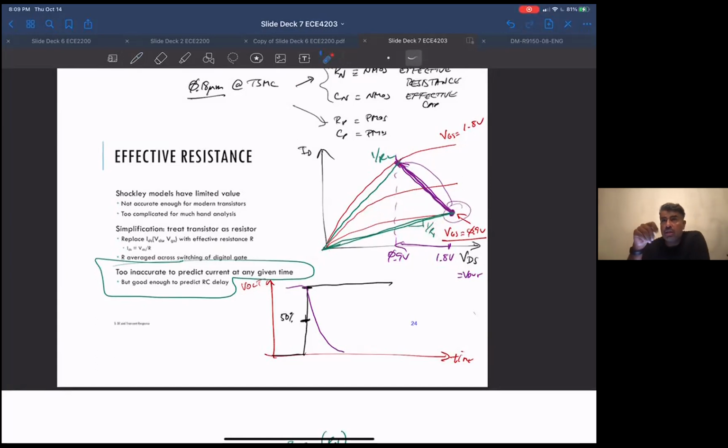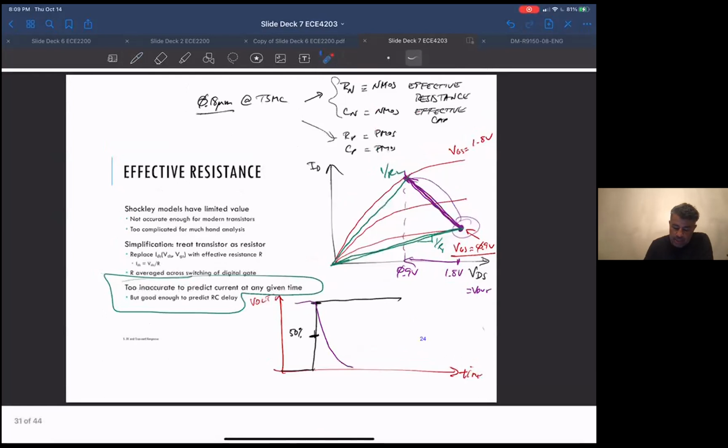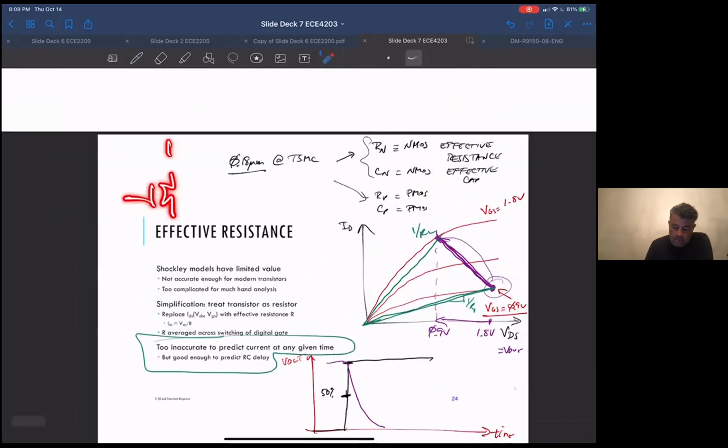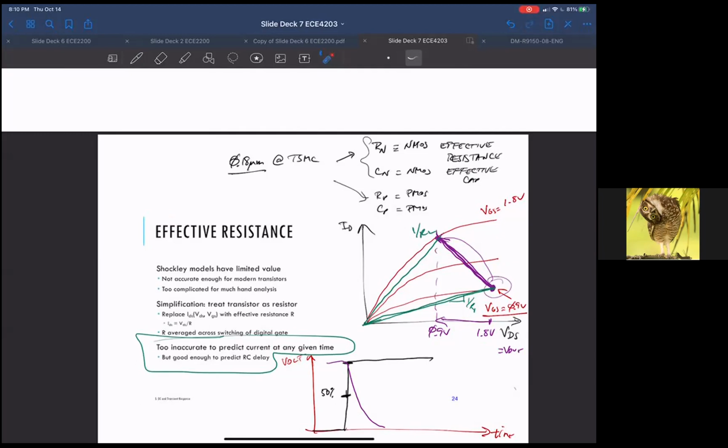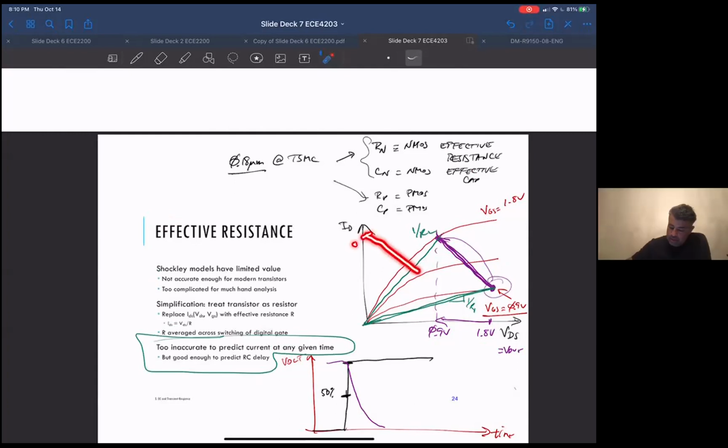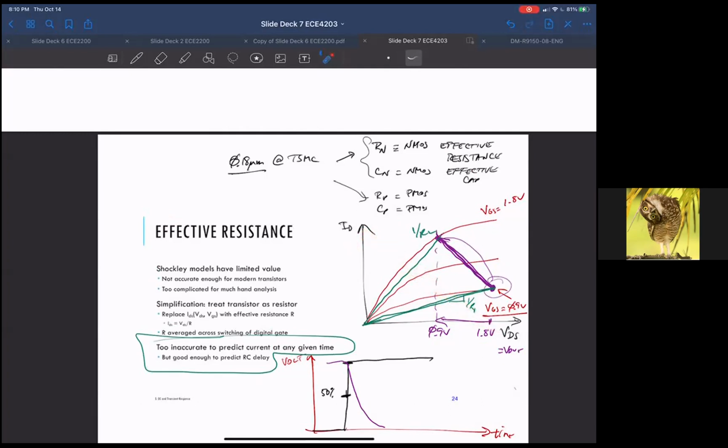Because remember, it's not a load line in the sense that we're not saying we have an NMOS and a resistor on it. We're saying we are pretending this NMOS is a resistor. And again, it's a really cheesy estimate, but that's what we're doing. Does that make sense? Yeah, for sure. It's similar to a load line, but an actual load line would have started at VDD with 0 for I. Exactly. I wish it was a load line.